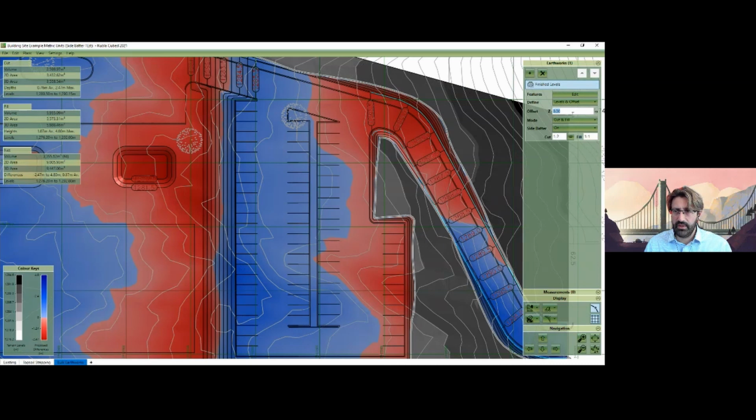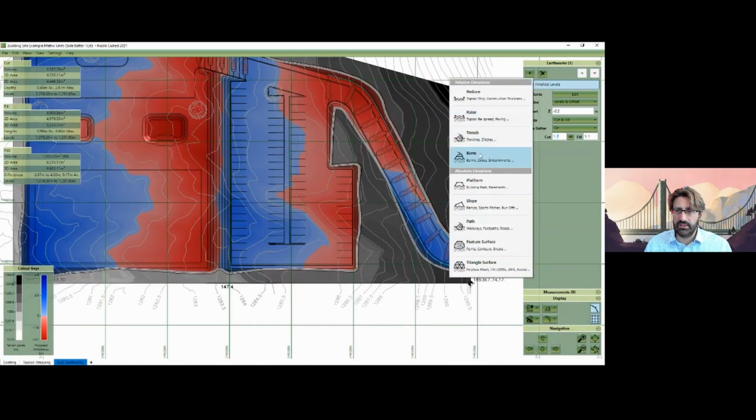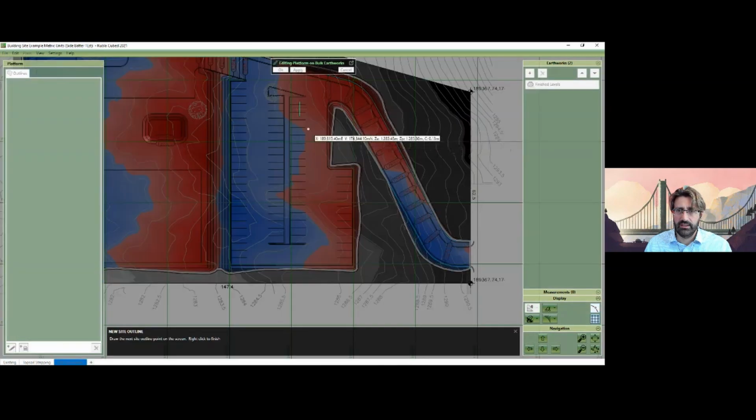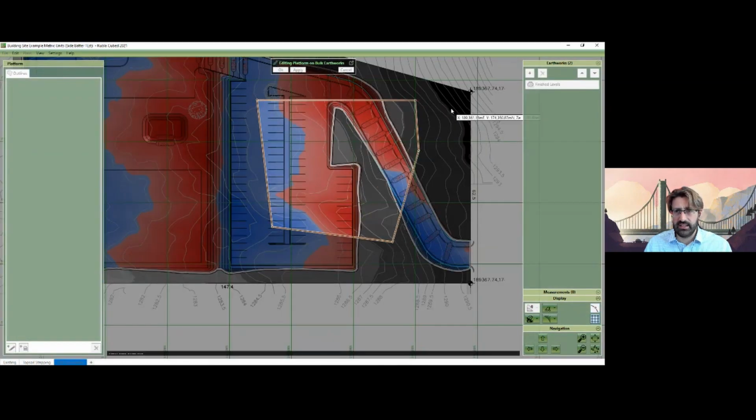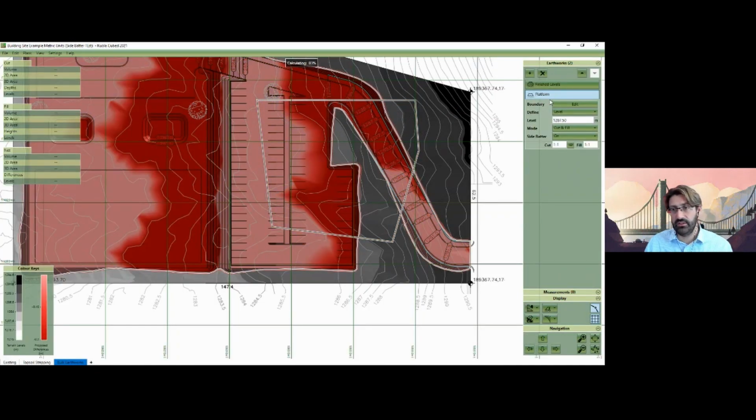So they might have an offset minus, say you have to put a negative offset for this method. We've got another building pad here, which is a platform. And where that intersects, because it's on the same phase and lower in the list, it will override the finish levels in that area.